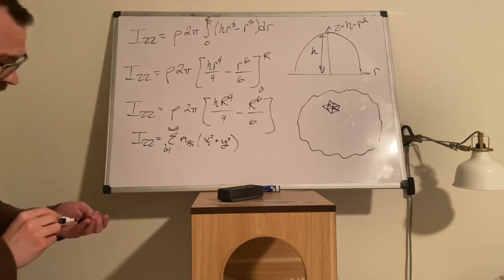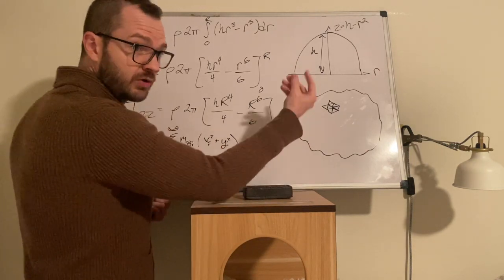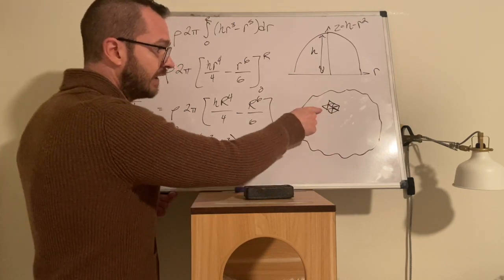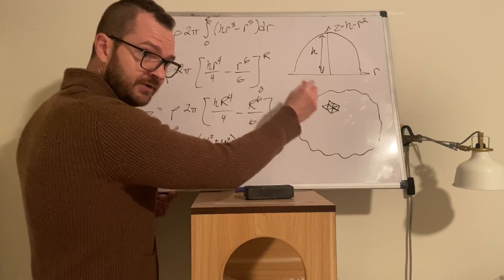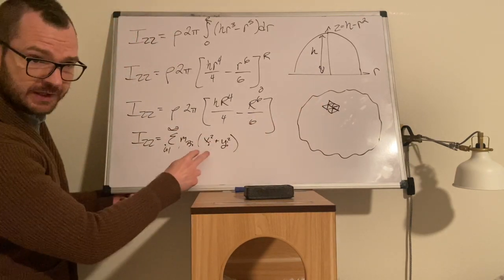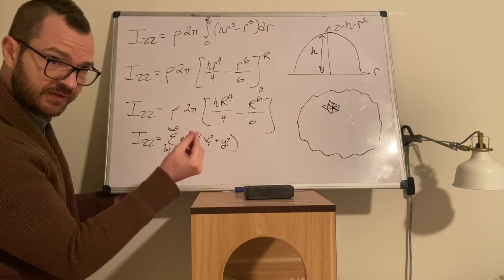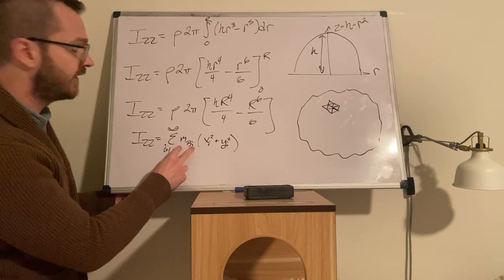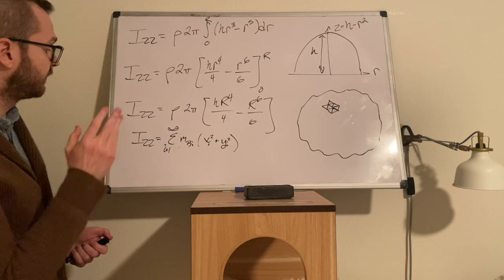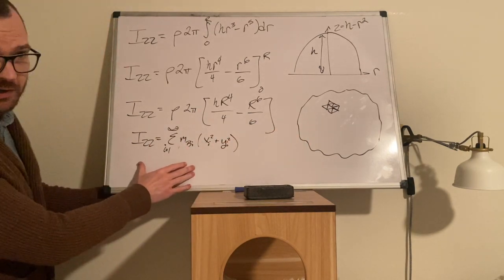And consider, in software, if it's applying a mesh to this, then you have some discrete differential bit of volume, and the computer software can find the centroid of that little differential bit. So numerically it knows x_i and y_i, and it can also find the amount of volume of that little bit, and then it multiplies that little volume by the density of whatever material you selected. So in modern day CAD software, this process is actually done numerically.